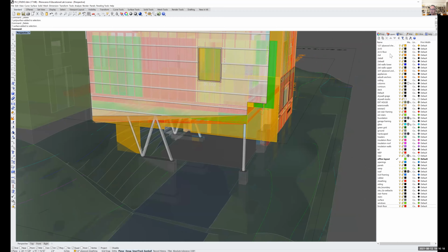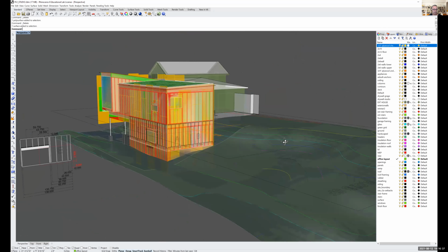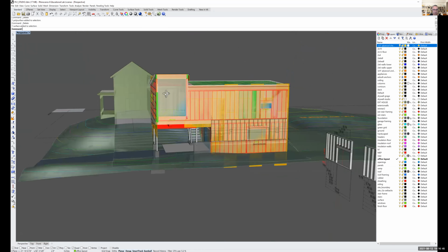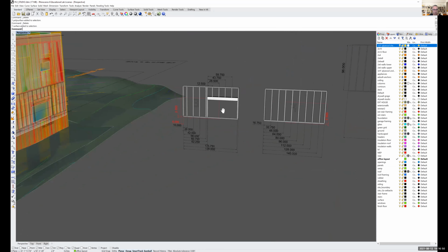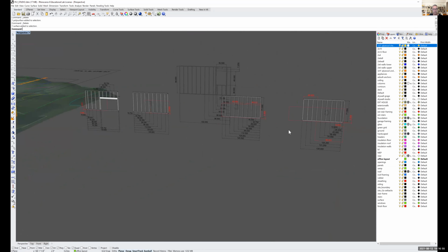And so, even to the extent we can see in the layers, that's the 1/2-inch plywood, 2x10s, 2x12s, 2x4s. So we use this as a way to get takeoffs for the model. And the layers are an easy way to begin to organize some of that and doing this all 3-dimensionally within the model. If I probably started turning a lot of these things off, it would start to look more like the design model that we saw a second ago. But even off to the side, we can see these were the probably individual wall panels that we were framing with key dimensions on there too.